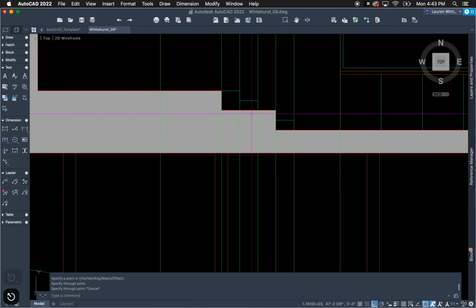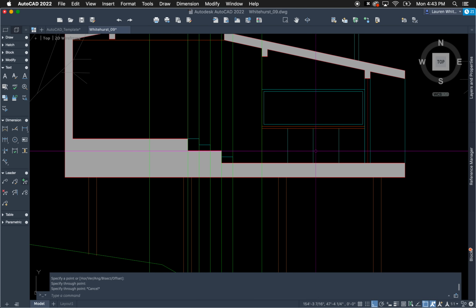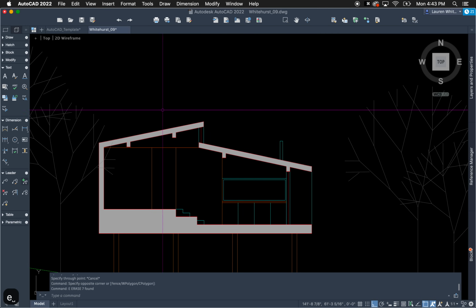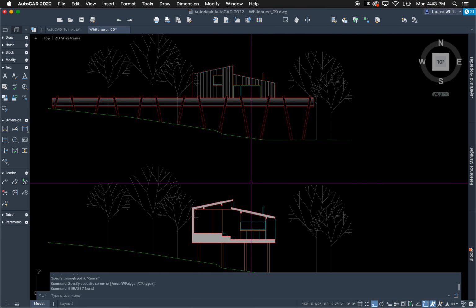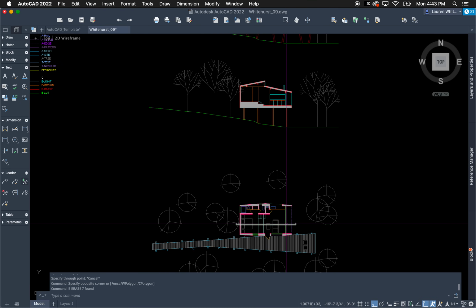And so if I pull all those lines up, that shows me vertically where something's happening in the drawing, and then the heights are the things that I used, just photographs or common understanding or dimensions like we did in the previous drafting exercise. So the height of this counter I have at 3 feet because that's a typical counter height. So using photographs and rules of thumb, you can get to a section drawing if you have just an elevation, or vice versa, pictures and the combination of the other drawings.